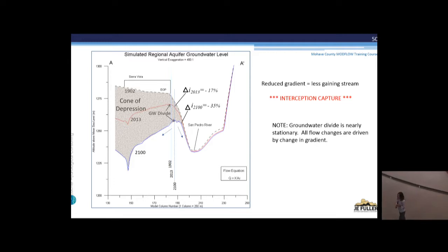They have rapid infiltration basins. They also have a wetland. They have a lot of wetlands, and then they've started to shrink that down a bit in favor of the recharge basins. But now they're concerned about the mound underneath the basins intersecting the surface. So there's a point where too much of a good thing can actually make it impossible to recharge, and you might have to move a little bit. And they're actually contemplating that issue.